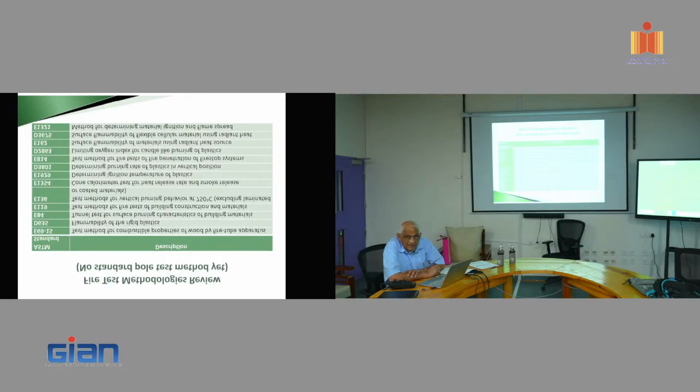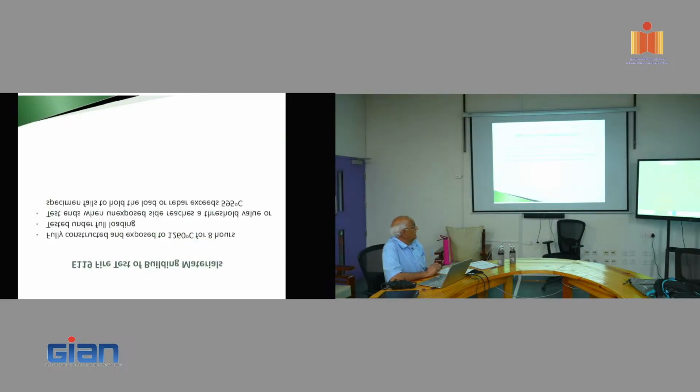There are many issues, I won't go through all that, but somebody was asking me yesterday, that's why I put it up here. The most important test is the corner test. That is the one. Here we have to take a full-scale specimen. Another important test is the tunnel test E84 and E119. We have to satisfy these two as a very minimum. And there are many others not quite as critical as those two.